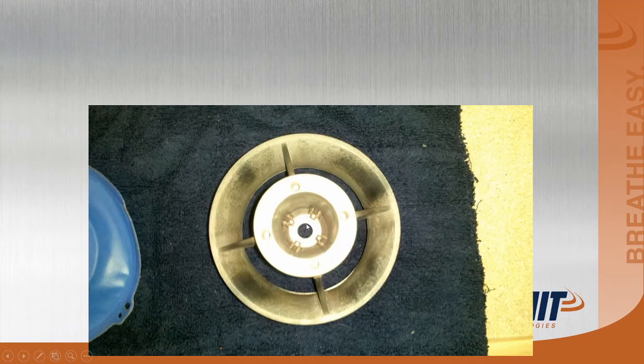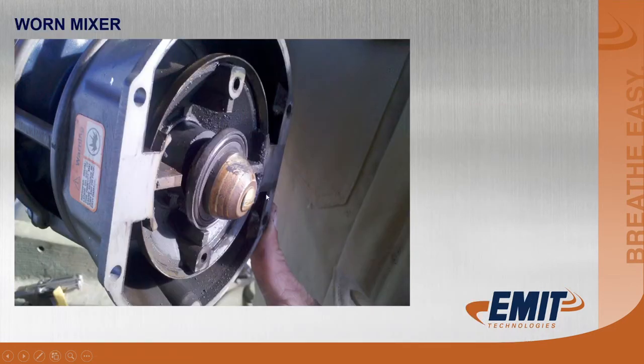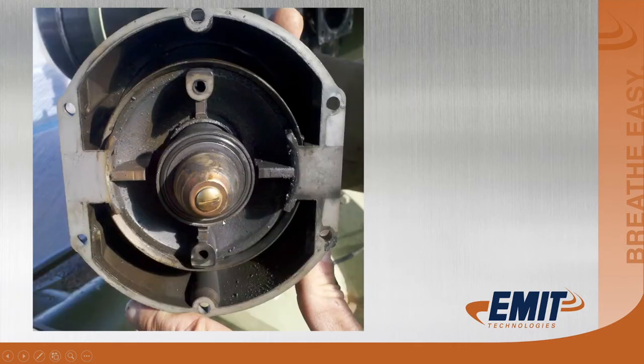Okay, worn out mixers. This one is worn out down in here. You can see this has come completely separated. This was on a KTA 19 Cummins. It was a side draft carburetor, and it became so worn and loose that this was flopping around and wouldn't align. It was a very hard starting unit and impossible to maintain emissions. It's just super imperative that carburetors and engines are in good condition for a unit to maintain emissions.